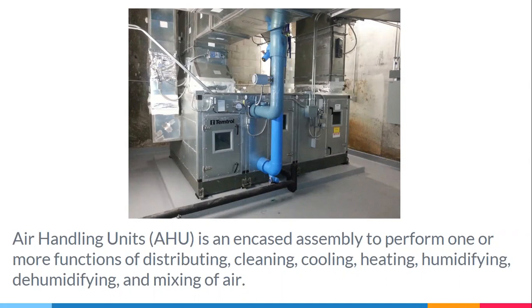So we're going to size up your fan and the pressure required for the fan. We're going to calculate the external only. So let me repeat. We're going to calculate the external static pressure, or the external pressure drop, for the air handling unit. The internal pressure drop will be dependent on the manufacturer.